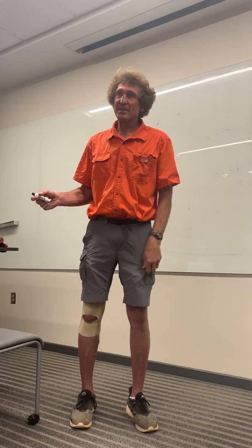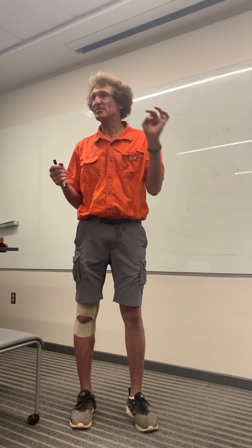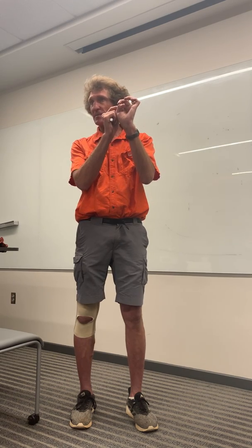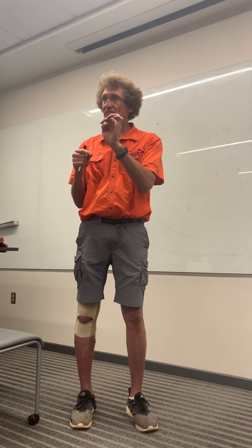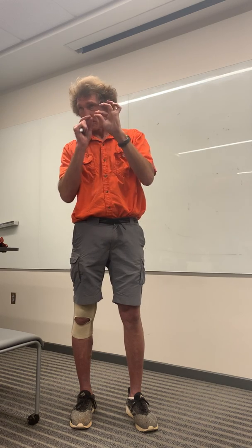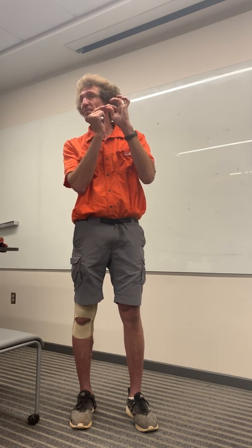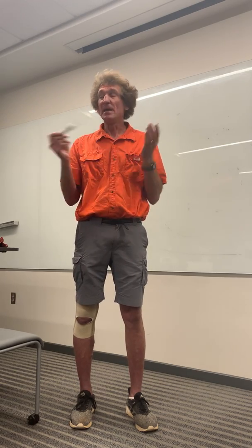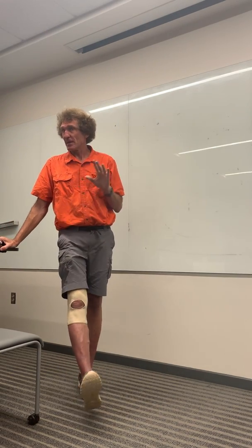So he went back, and thank God he inspected it. And one of these guys who did the soldering put a big fat solder ball on one of the leads that connects to the coax. Now what that does is introduce a large inductance by accident. Instead of having a matched system where all the wires were short and soldered perfectly, we had a very unmatched system. So he went in with a soldering gun, cleaned it up, and connected it back. And the VSWR then was about 1.2, something like that, which is acceptable, and the antenna worked.